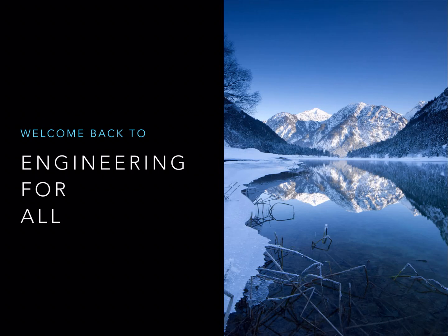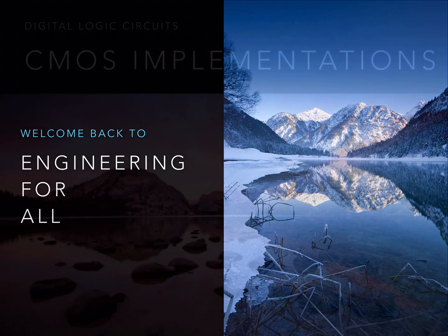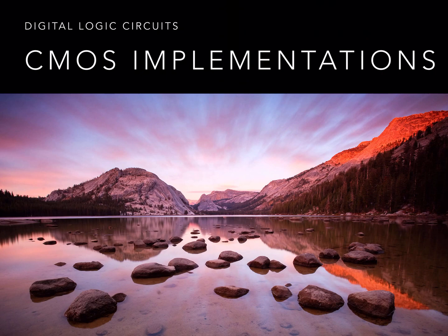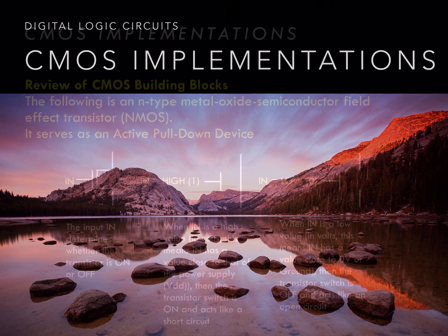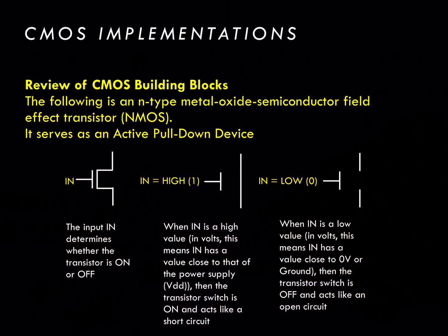Hello, and welcome to our session on CMOS implementations of digital logic circuits. As a review, let's take a look at the basic CMOS building blocks, NMOS and PMOS transistors. In the digital world, transistors are modeled either as open switches or closed switches. An open switch is modeled as an open circuit, and a closed switch is modeled as a short circuit.